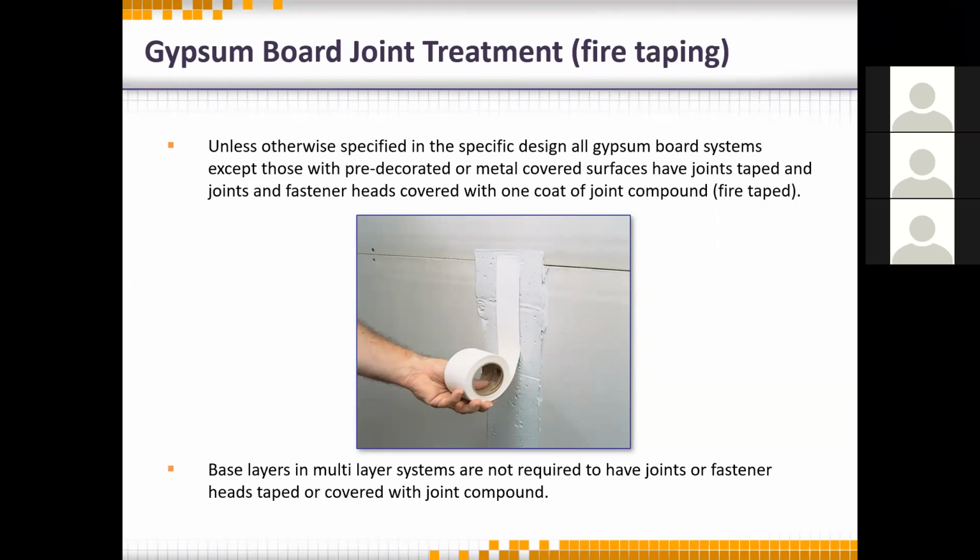For multiple layered walls, 2-hour, 3-hour, 4-hour walls where you've got multiple layers of drywall, we only fire tape the outside or the last installed layer on both sides, okay? That's it. We don't have to do every layer.